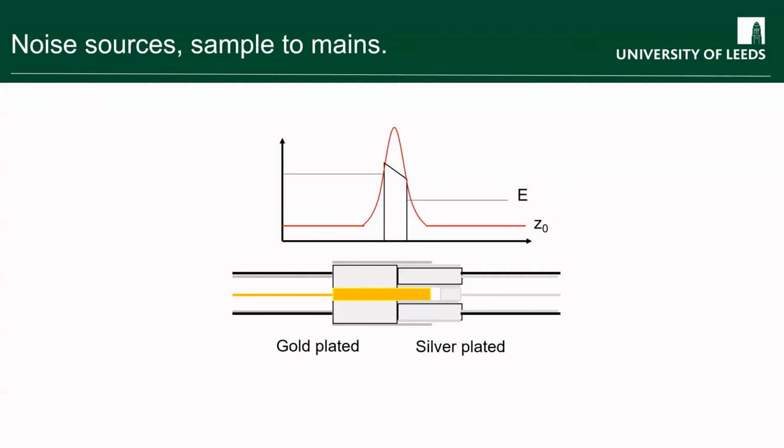On the point of connections, connections are often a source of noise problems, and there's a couple of ways that they can introduce noise. So first of all, if they've got different materials and you've got a temperature gradient, then you've got a thermal EMF there, and that can fluctuate and therefore give you a source of noise. If it gets a bit damp, and especially if it gets a little bit salty and damp, then you can set up an electrolytic cell, and you can generate voltages like that, and you can also cause your electrodes to start corroding. If your electrodes have some surface oxide on them, then you have a potential barrier, and now you're starting to think about electrons tunneling across a potential barrier, so you're introducing shot noise. So in all these different ways, you can end up introducing additional noise into your measurement unintentionally.